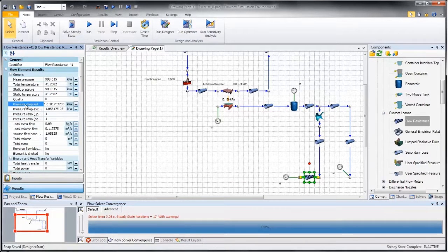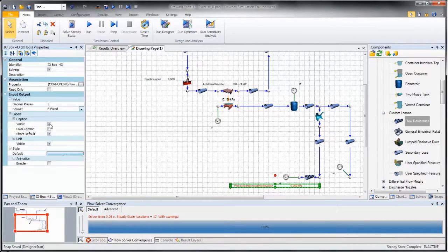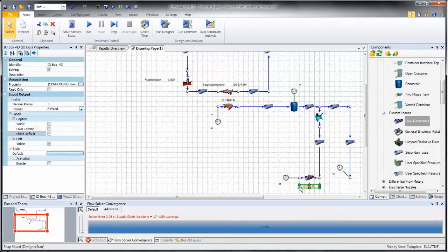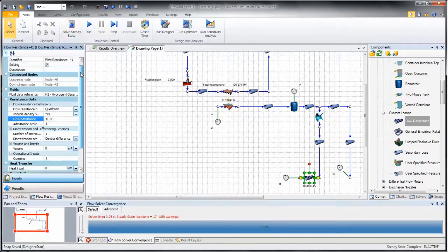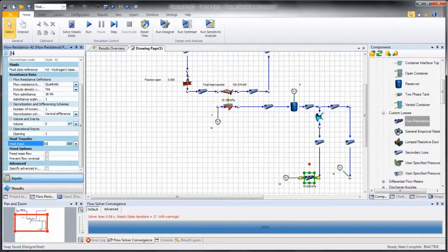Let's get this onto my canvas. So I can increase the resistance by 1,000,000, or in terms of admittance, decrease by 1,000,000. That looks good. Now let's add the 50 kilowatt heat load and solve again.